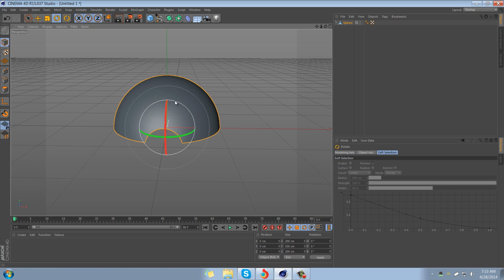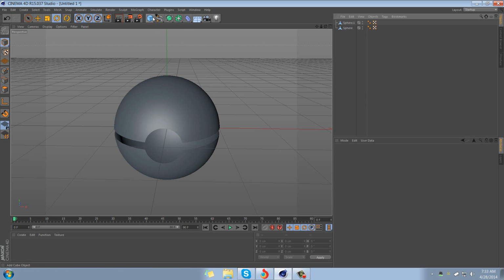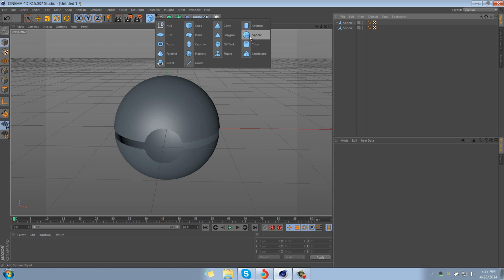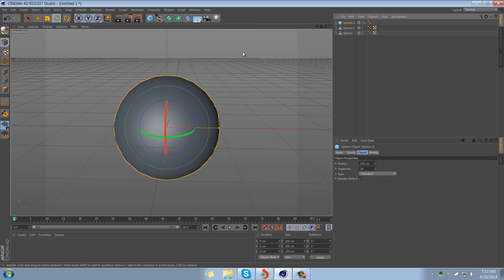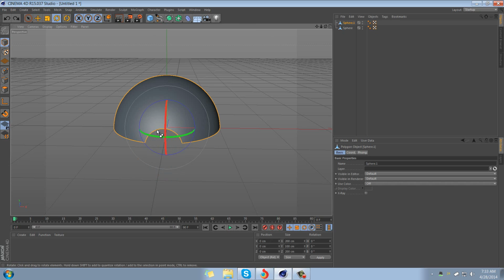So I'm going to go to the rotate tool and along the blue circle here. Actually, we're going to Control C, Control V to get a copy, and then along the blue circle, rotate it over 180 degrees with your rotate tool. Alright, and then we're going to come in here, the top again, and spawn another sphere. Actually, there was one step I missed, so we're just going to go back and do that quick.